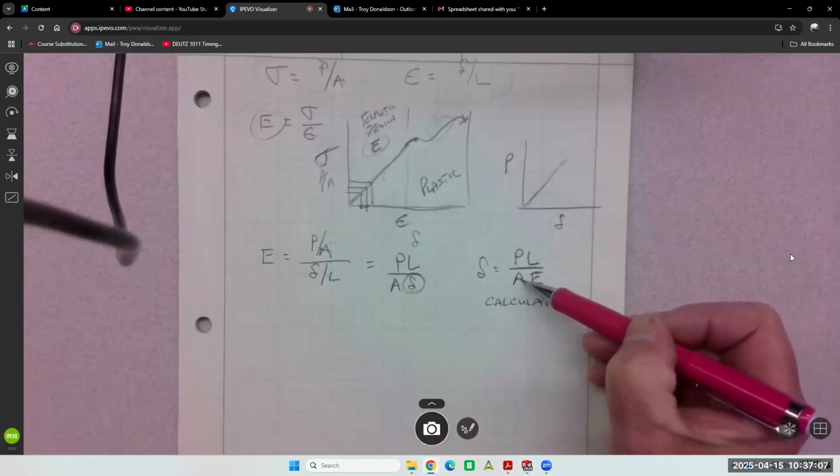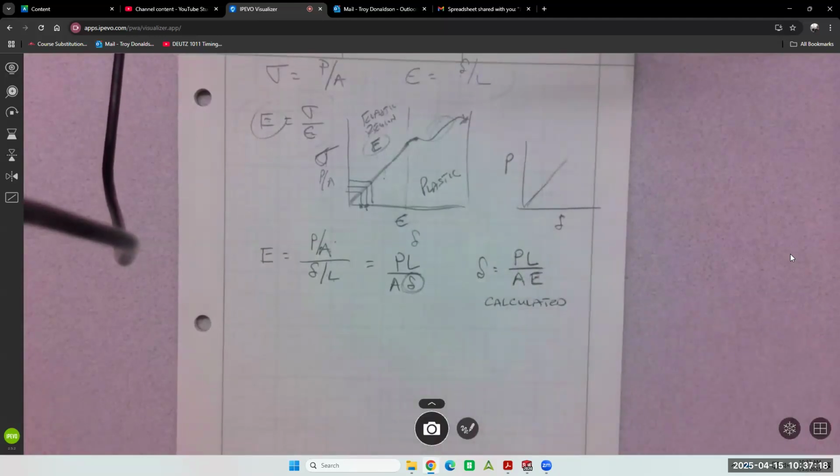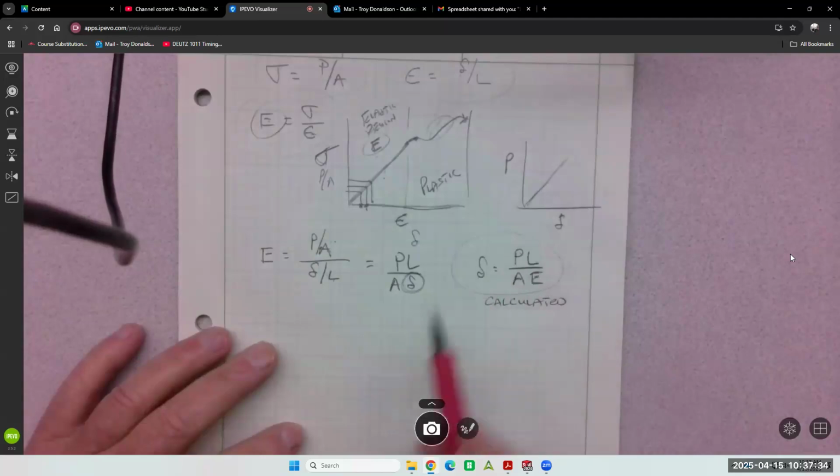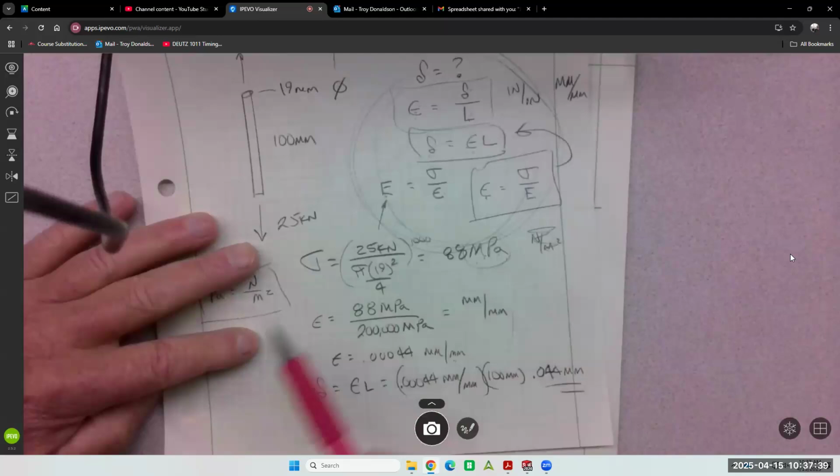This is the shape property, what shape it is. Is it a pipe? Is it a W shape? Is it a rectangle? Whatever. Length and load. If it was a pipe, you would only do the area of the pipe, just of the material. Most pipes you can look up, so you don't have to calculate that, but it would be just outer diameter minus inner diameter. You could get it. Yeah, so this is exactly what we just did here.